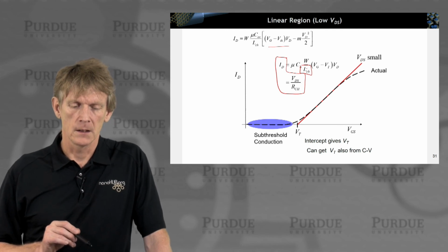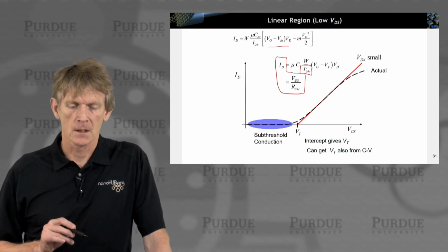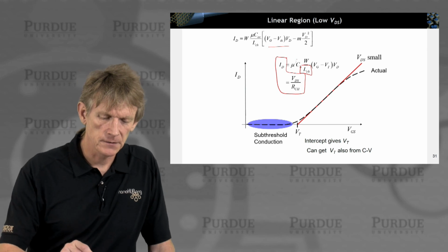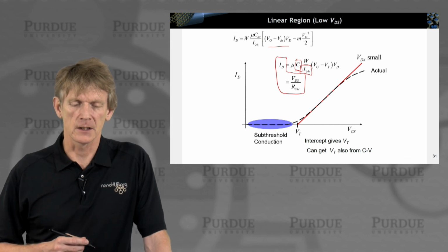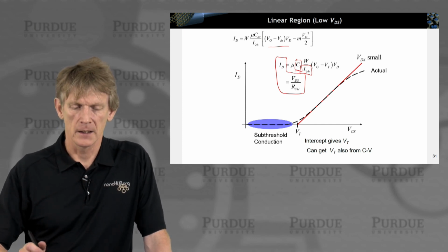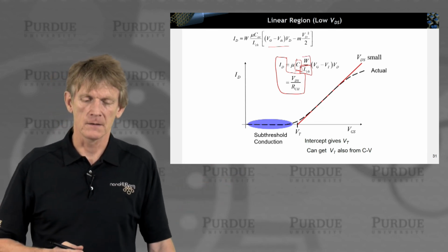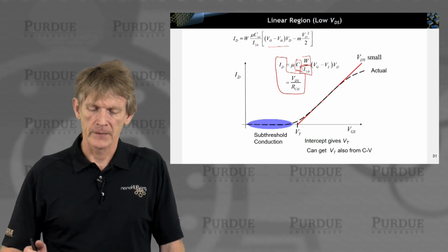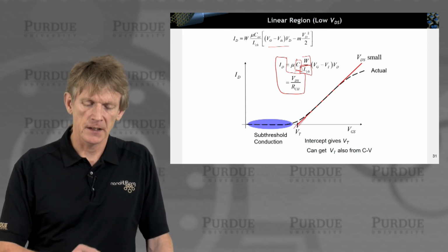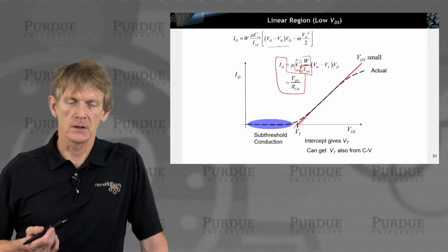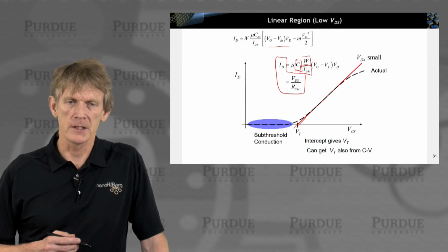It goes down with mobility going up. And there's a capacitance in here that's kind of describing the width of the channel, if you will. How many carriers can you get into the channel, right? And it goes as W, the wider you make your transistor, the more current you will have flowing, right? Now, in this expression, you have an intersect with VT, that's your threshold voltage. That's how you start to turn on your device from depletion into